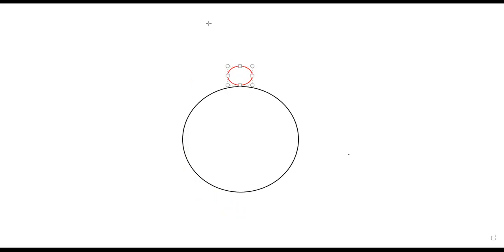And we also have another type of equilibrium, that is the neutral equilibrium. So if this is any stationary surface, and I have a roller here, in this case, if I give any displacement to the roller, it will attain another equilibrium position. But throughout this displacement, either in the right direction or in the left direction, the potential energy of this system is constant. The potential energy of the system isn't going to change.